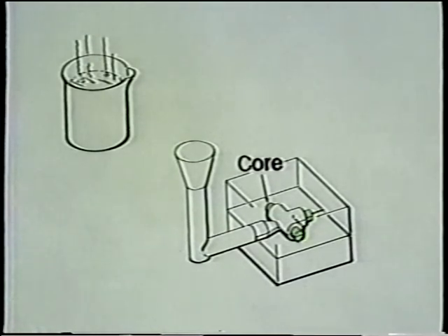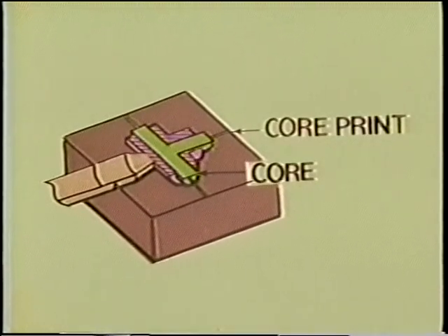The core is a specially formed material which is inserted into a mold to shape the interior of a casting. A core is supported at either end by core prints in the mold system. Cores may be sand, ceramic, or metallic in composition. Non-metallic cores are not reusable and can be removed from the casting by dissolving in caustic media or by mechanical agitation. This ability to easily shape the hollow interior of a part is a unique and valuable advantage.